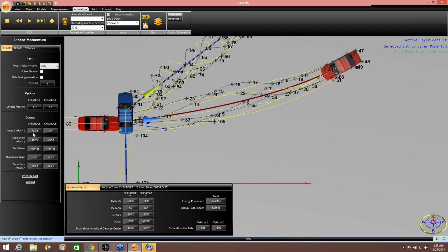But I've got to justify why I use that deceleration rate. So when I used a 0.42, I can justify that. Because ground friction is a 0.7, rolling friction on these cars was somewhere around a 0.2, I went right in the middle of it. Because you know what? Sometimes they were rolling and sometimes they were sliding sideways at the full friction. So I can justify using that average in the middle somewhere.